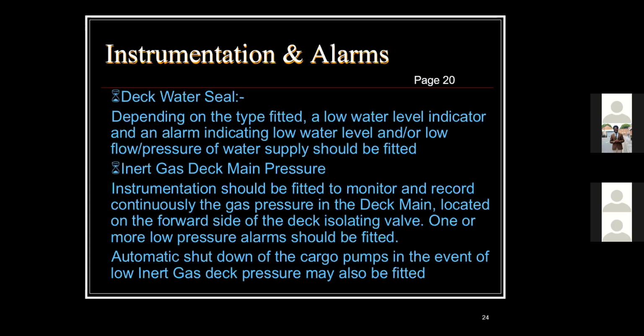And quite often, if you are in a tanker, you want to take precautions while the vessel is alongside. Once you are loading, if there is lightning in the vicinity, what you tend to do is shut down the vent riser and sometimes reduce the cargo loading rate, so that you don't generate so much inert gas as to overpressurize the tank.